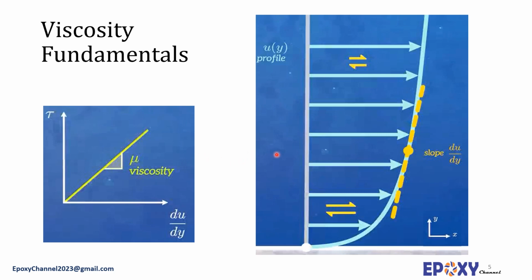The maximum shear is at the wall as we have no-slip conditions, meaning that the fluid is stagnant right at the surface. And far from the surface, the fluid layer cannot feel the wall at all. The slope of this curve changes and it is large near the surface. It shows that by changing the distance, the velocity changes substantially.